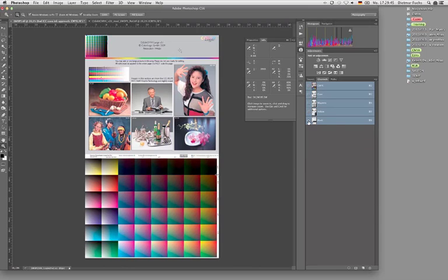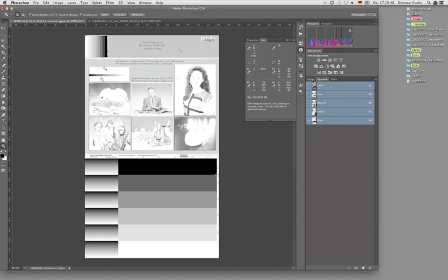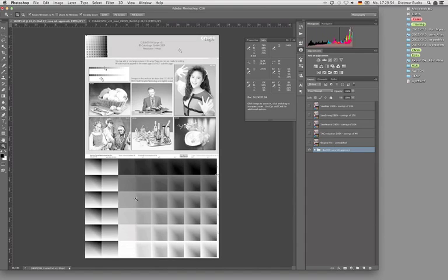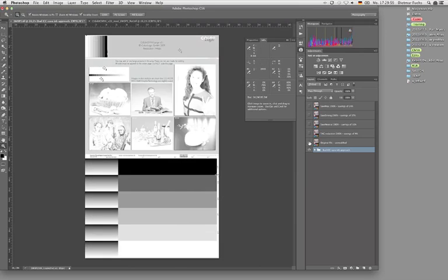If I'm just showing the black channel of this file, using the ICC conversion, it would look like this. I have a complete reseparation, and my black is changing. That's not what I want. I want to keep this and only reduce the TAC where needed. And that's what this TAC reduction profile will do. You see that was the original one, and that's the TAC reduction profile. It will only change black in those areas where it's absolutely necessary, in this area, or for example, in the hair of this lady.